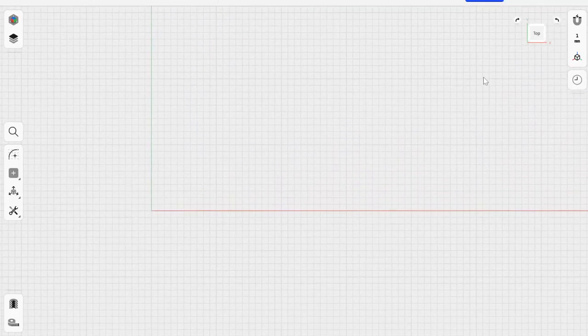Right. Once I've got the orientation that I want, the other thing I'm going to want is to make sure that the size of the grids are what I'm wanting to draw on. So at the moment, you can see here, mine has gone to 1 millimeter. So that means every square here will print out to be 1 millimeter. And then the darker lines are every 10. So that means this larger grid of darker lines will be 1 cm.